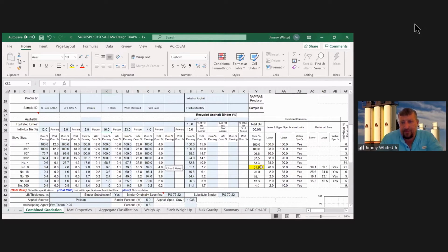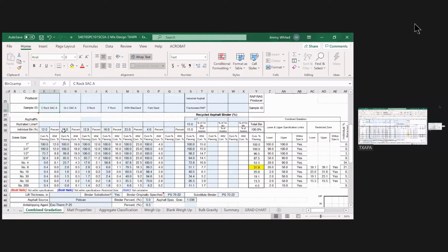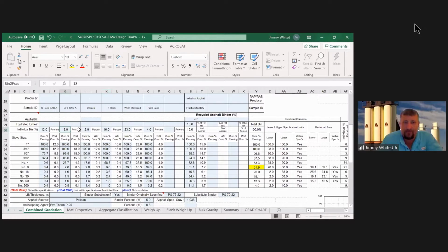As you can see, we pushed it down even more. When we did that, this is, like I said, a river gravel mix, so you got super low absorptive aggregates right here on these two. You want to keep your C down. You don't want a lot of big rock. And that's where a lot of people make a mistake when they're trying to coarsen their mix up. They put too much back into the top end. You want to put as little as possible on that top end, because that'll save you from segregation issues in the field. That's a good point, Joey. Thanks for saying that.